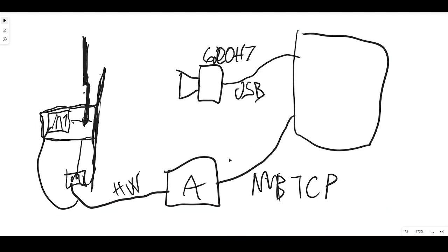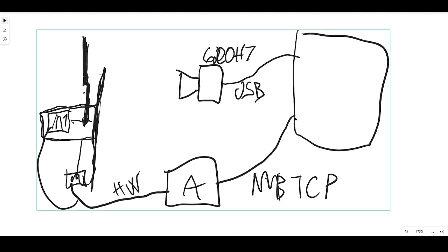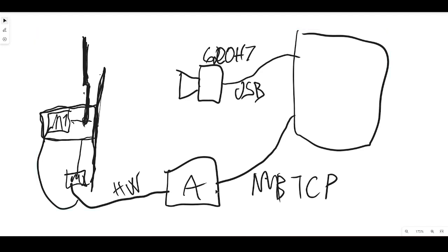Most Arduino examples I found were via router. I didn't want to use a router between the PC and the Arduino. Then it's hardwired signals to two motors, one for swing, one for cart travel. And then the position is fed back through these color patches again to the camera.